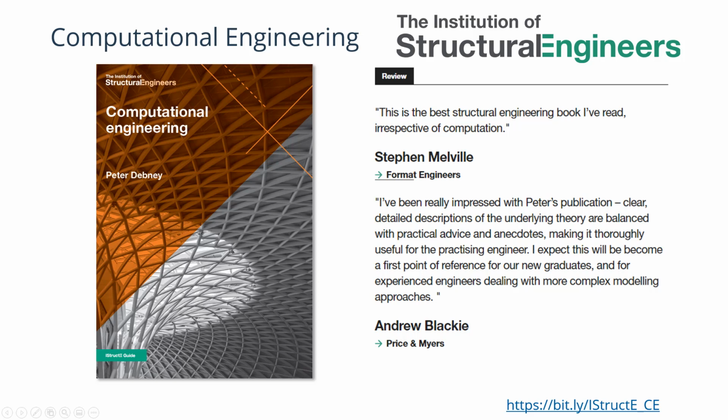Any recommendation on applying stiffness modifiers in gravity load analysis? Most people reduce the stiffness of slabs and beams for gravity load analysis too. It doesn't make any sense to me; any recommendation on this? Yes, so it's tricky. I presume we're talking about concrete structures here. In concrete structures, the stiffness varies as the bending moment increases.